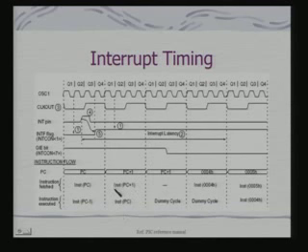Now, what we will find here when we look at the instruction flow is that at this point I was actually executing the instruction which was pointed to by PC here, and I had already fetched the next instruction because that is basic pipelining in the PIC processor. But since the interrupt has occurred, what will PIC do? It has to respond to the interrupt and start execution of the instructions from the ISR. So, you will find effectively a dummy cycle is introduced here, which I was referring to as NOP, nothing happens